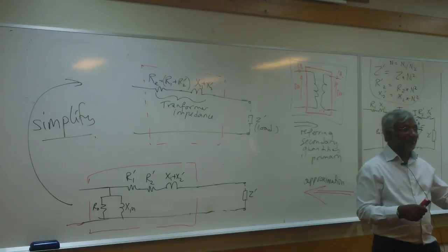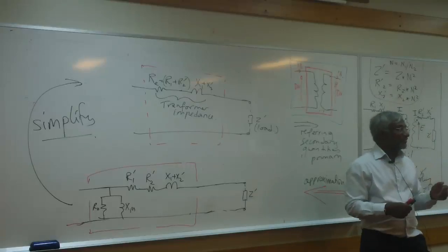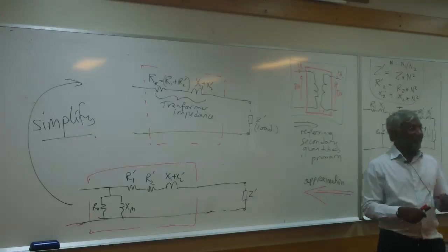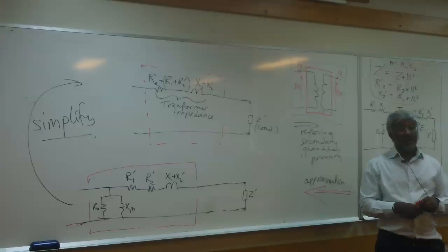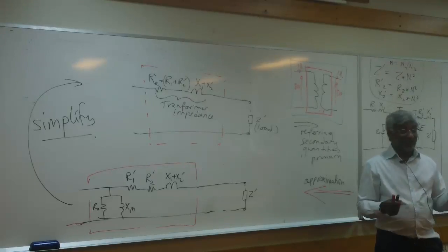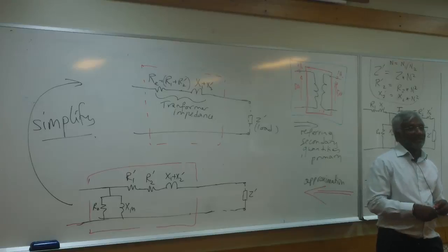The one that's in trouble would be automatically taken off the system and the load will be supplied from the one transformer. That's one reason. Of course, there's another reason to have transformers in parallel. That would be if one couldn't supply the full load, then they could share the load.